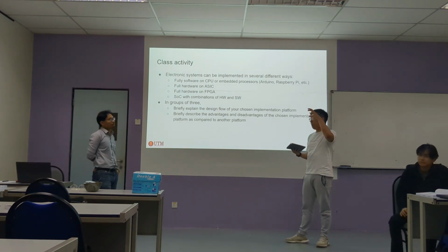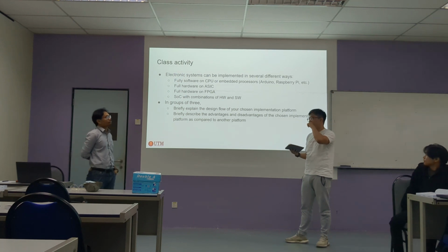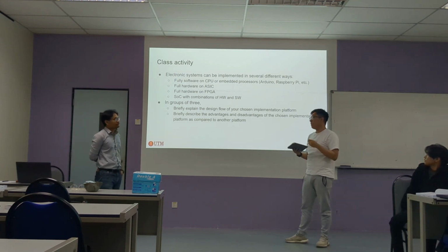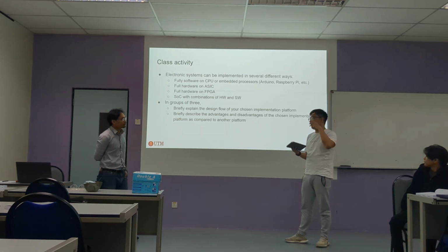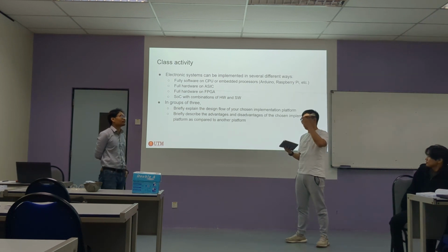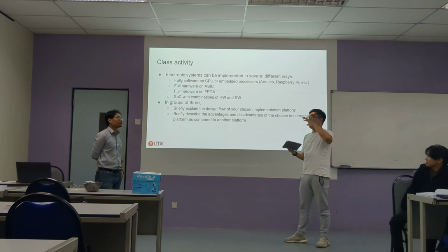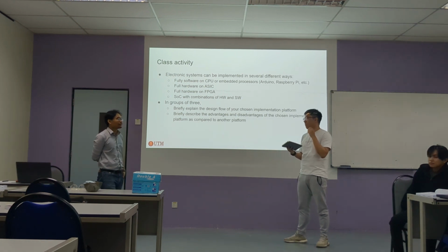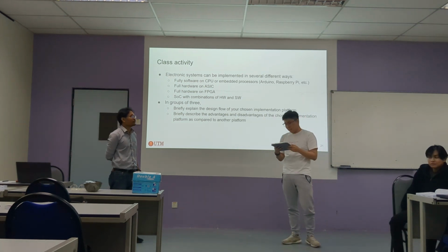Then we pass the front-end designs to the back end, which is the physical design: floor planning, placement and routing. They run a post-layout simulation and compare it with the pre-layout simulation. If the specs still fit, we can proceed to fabrication. The post-layout and pre-layout steps go back and forth, so it requires a lot of slack time in the design.